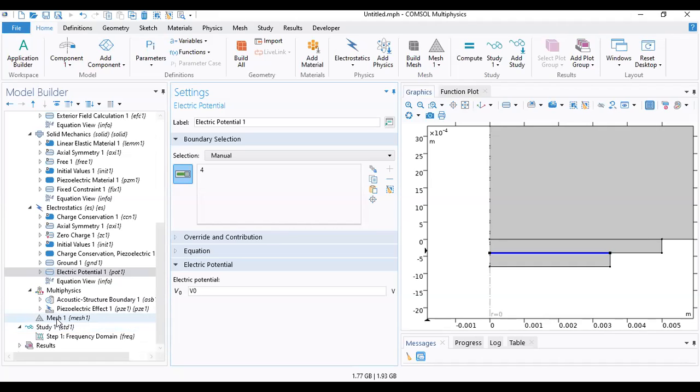The mesh part in the acoustic modeling should be carried out with full consideration. COMSOL can do it for us, but we also need to do some operations on the mesh part. As you may know, in modeling pressure acoustics, you should be assured that the mesh can resolve the wave propagation, and you should set up your mesh with respect to the wavelength and frequency.